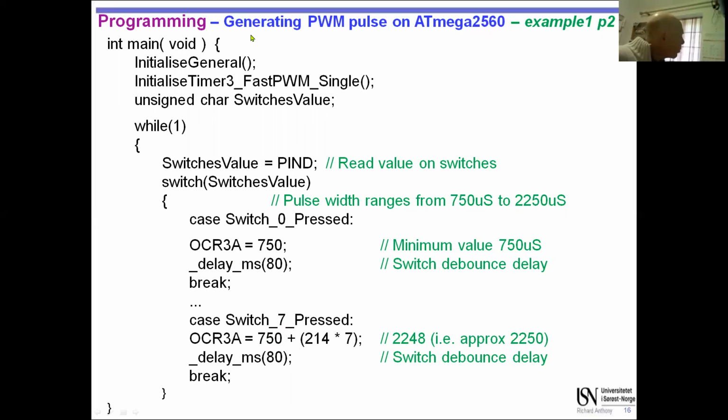Okay, that's just simple control. There's nothing about servos in here really. It's just simply switches and setting a value in a register. But that's the important bit, because that's how the user would control it. This is the register value that controls where the servo would point. It's this number, plus that, and if you add that up, you get almost exactly that, because obviously we can't do fractions. So this is the closest I get, but that's pretty good. It divides it pretty accurately.